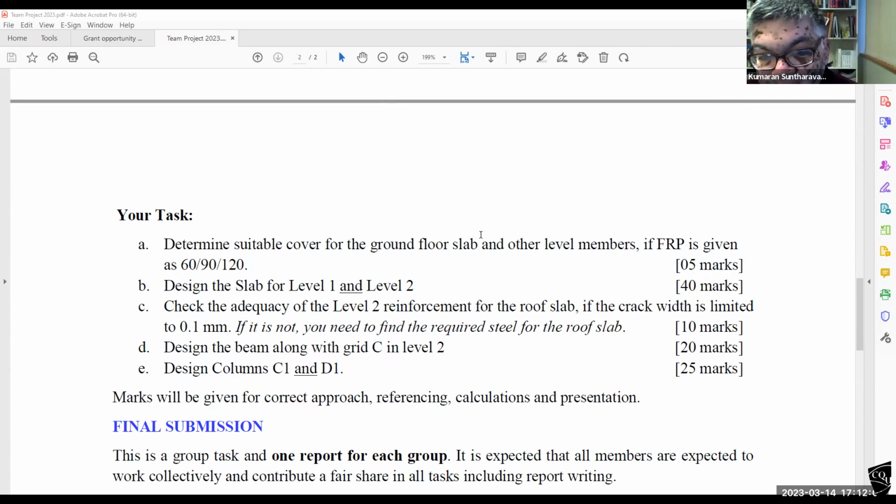And you also can calculate the superimposed dead loads, which come from the marbles or the tiles weight and the ceilings. All the required weights are given in Appendix A of 1170. The densities are given.